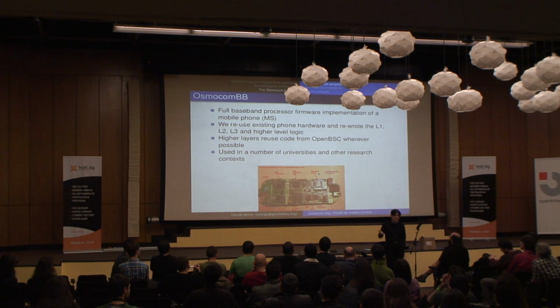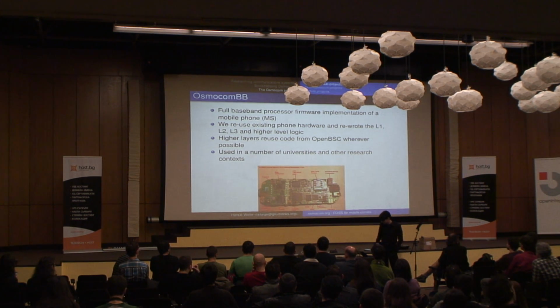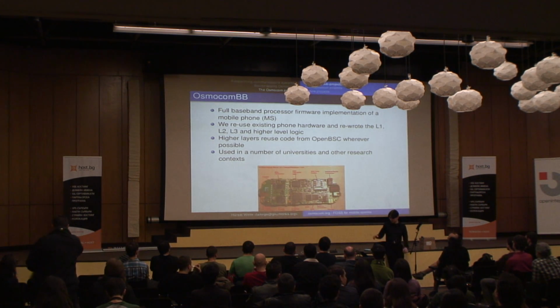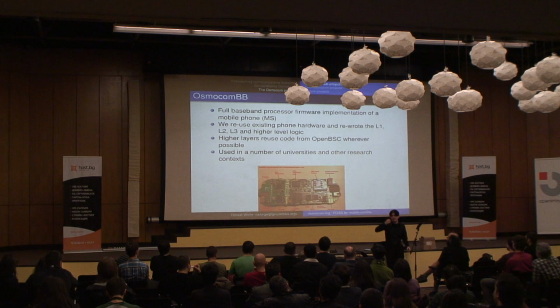We reverse engineered that hardware. We removed the original software of Motorola and Texas Instruments, and we rewrote that protocol stack that runs inside the phone. So you can use such a phone now and connect it over a USB cable with your PC. And then the phone just acts as a stupid transceiver between the radio interface and your USB cable. And the entire protocol stack, layer 2, layer 3, mobility management, call control, SMS, authentication, everything runs on your PC and in open source software.